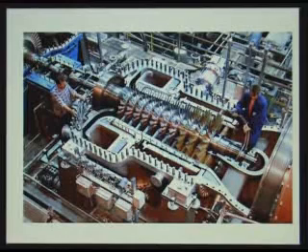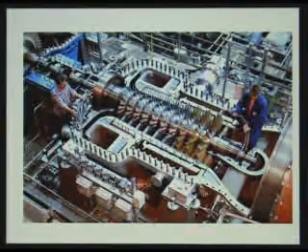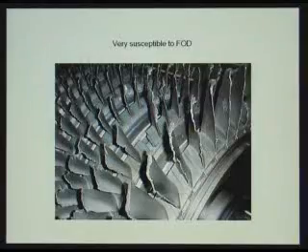You don't get a tremendous pressure rise across each section, which is why you don't get a tremendous pressure rise across the compressor as a whole, but it does handle a very large amount of gas. But also because there are so many of those stationary blades that are so accurately machined, they're very susceptible to foreign object damage, and this is what happens when a little bit of weld splatter in the process pipe breaks loose and comes in and starts bouncing around.